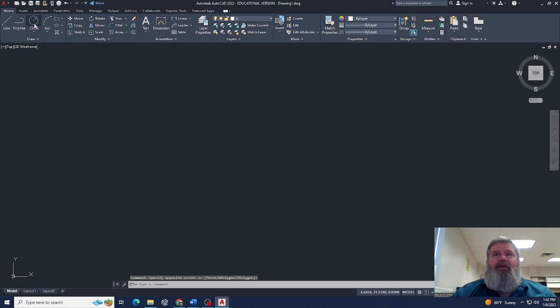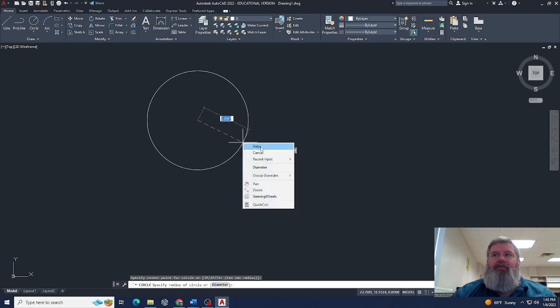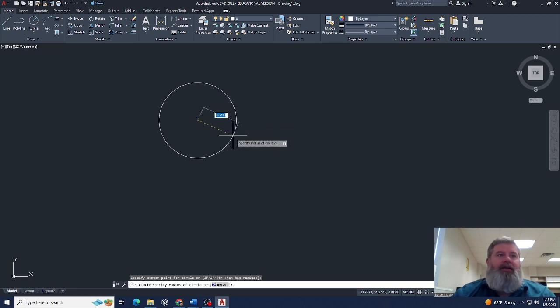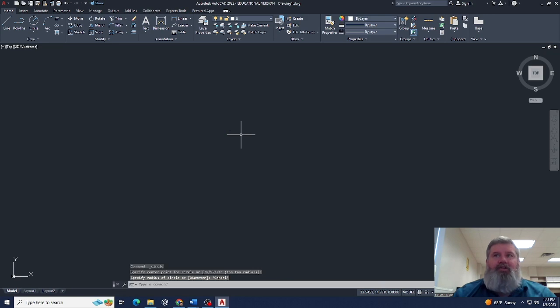Now, say I'm in a command, say I want to draw a circle, and I'm like, wait a minute, I don't want to draw a circle. How do I get out of this? So if I try right-clicking, that doesn't do anything. That's just going to set it. So how do you get out of that? In order to cancel a command, you hit the escape key on your keyboard. That is the upper left-hand corner of your keyboard, the escape key. That is how you get out of that.